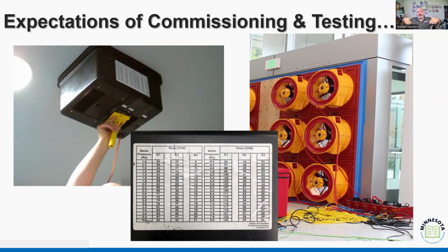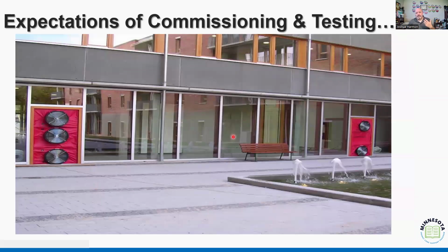If it goes into that attic, it goes in that crawl space, it goes where the duct runs out through an unconditioned warehouse space. That's when we're looking for it. And in those buildings, again, we're seeing a system that's a little bit more robust than just a single blower door fan, right? But ultimately, what we're trying to do is pressurize the space so that we know how well it's working and how that system is going to operate when it comes to maintaining the temperature.